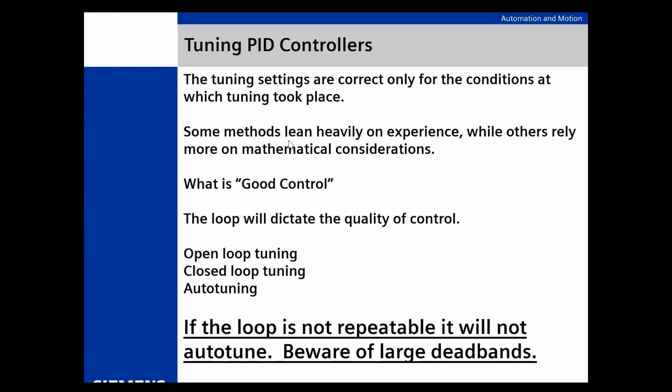And again, like I said earlier, beware of large dead bands. Somebody couldn't get it to tune. Somebody wants to see a flat line. I'll throw enough dead band to get a flat line. Something else you need to be aware of: in most instruments you can add dead band in the instrument, and I can add dead band in the system too. Make sure everybody's on the same page here. Make sure you're not adding dead band and the guys in the field aren't adding dead band, because now you've got nothing but dead band. Make sure you know what's going on out in the field with that dead band.